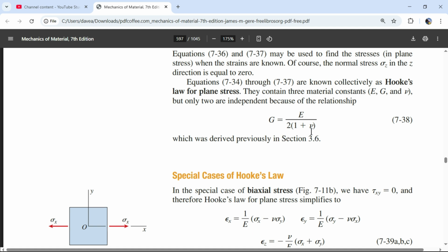So if you know Poisson's ratio, in the back of the book is 0.3, and this is E, then you know that 1.3 is going to go to 2.6, and you have 29 divided by 2.6. So that's where you get a value of about 11 million. This is 29 million divided by 2.6. You get about 11 million. I can buy that.